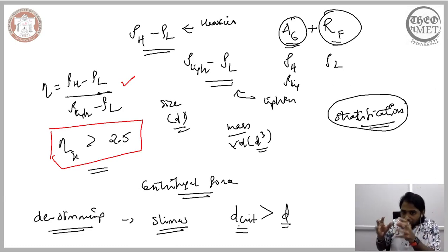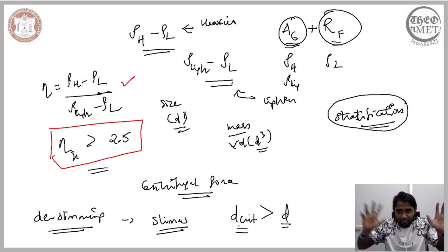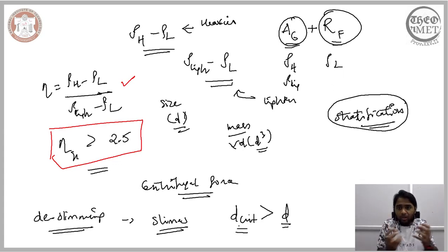Now, when you consider the mixture on a realistic scale, there are particles that are smaller than the maximum size that can be handled by the gravity separation process. These particles need to be removed, or else they get mixed up, suspended, and apparently dissolved in the medium, thereby increasing the density of the medium and interfering with the overall efficiency of the process.